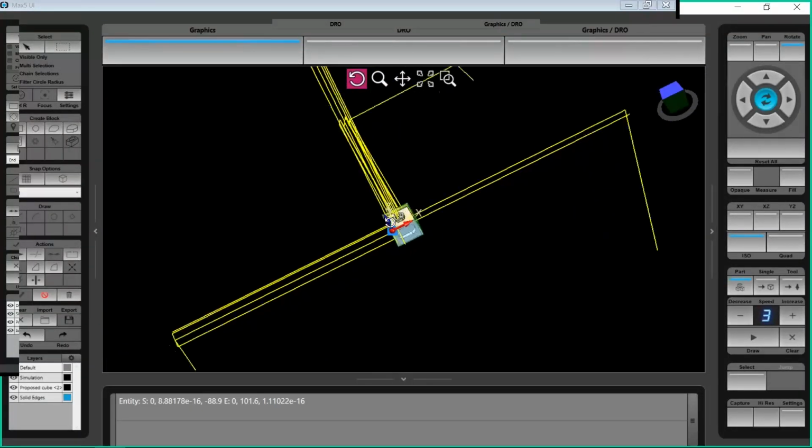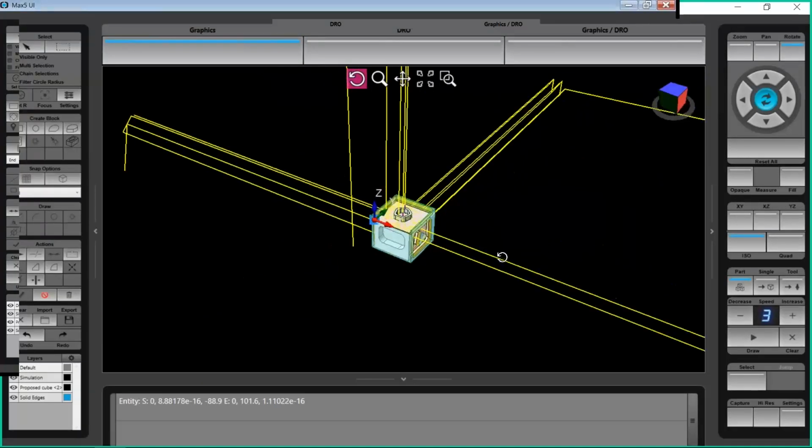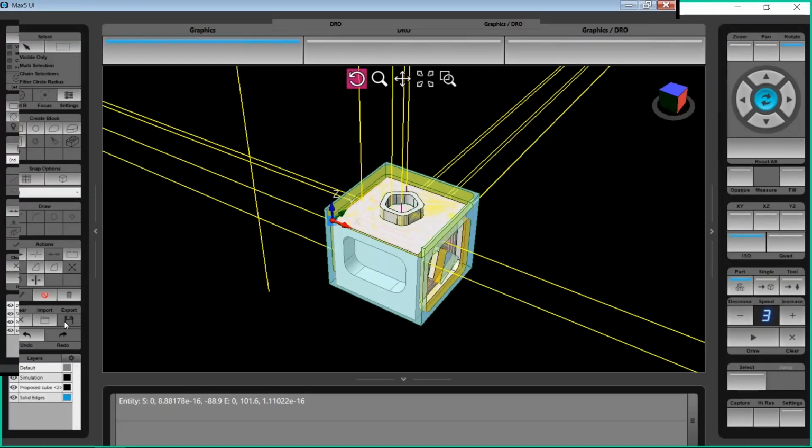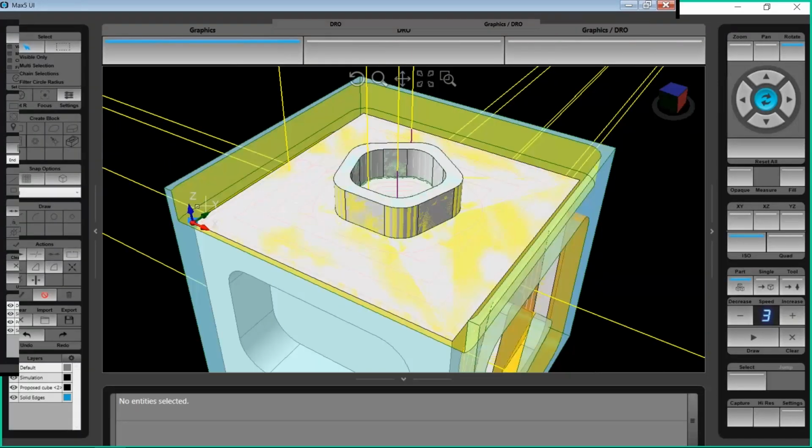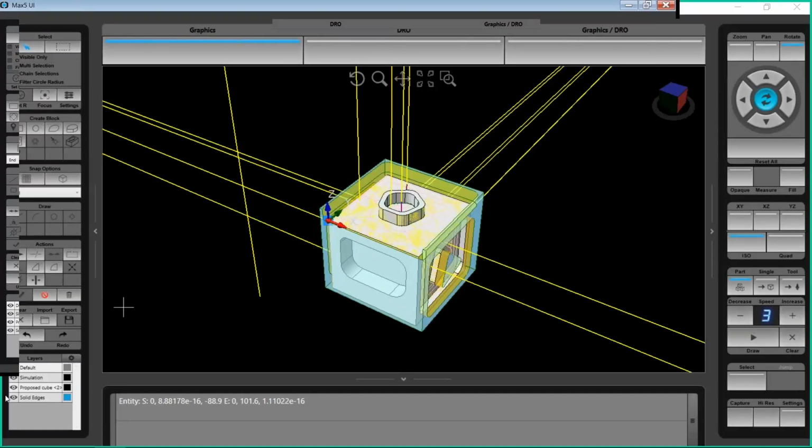Okay, at this point, guys, I want to point out one more thing here: the export key is locked out, so I can't export this if I had made any changes. You can only export that 2D geometry. But what I also want to do is show you moving, rotating or transforming the origin point, where it is on the block. So what we're going to do is select that origin point. We'll zoom in there and go ahead and select it. Excuse me. Let me hide my simulation.